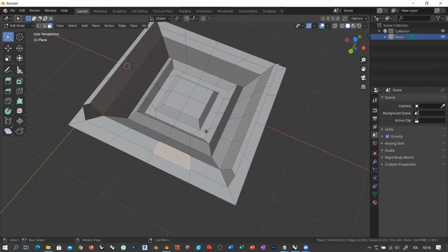In that case, I can go with the mouse close to the cross edge, referring to the direction that I want to consider, which is this one. The cross edge is this one or this one, whichever you want to consider. If you go here with the mouse and then you Alt click, then you are selecting the whole stripe of polygons in that direction.